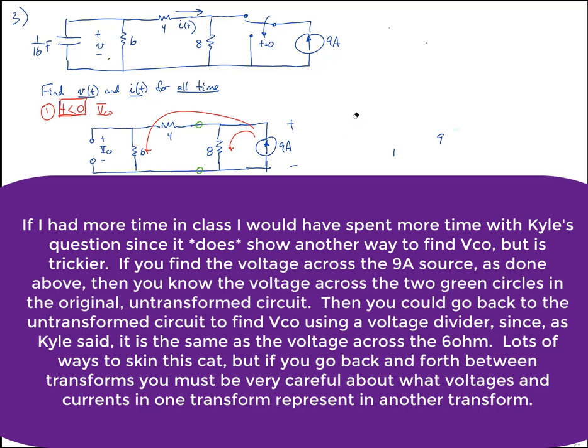So whatever you do, you can't destroy that 6 ohm resistor, because if you do, you've destroyed the thing you're trying to find. Okay. Really easy to do, which is again why you need to write down what that voltage is across that open, even though it's an open and even though it's not affecting your circuit. Otherwise, it's not affecting your circuit, but it sure as heck affects the way that you solve it.